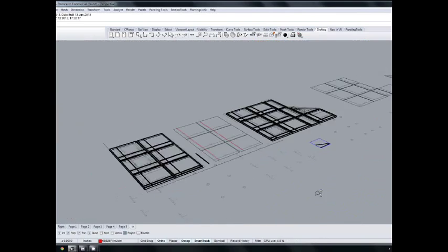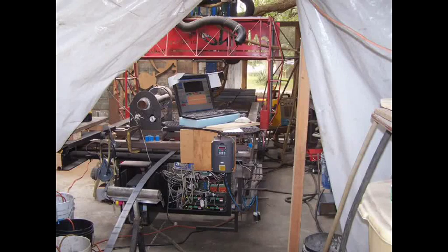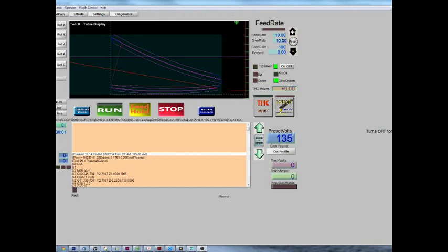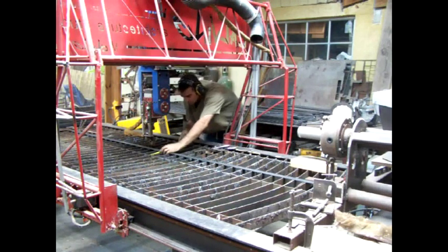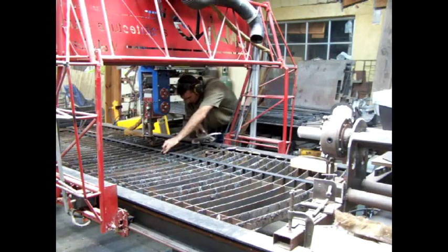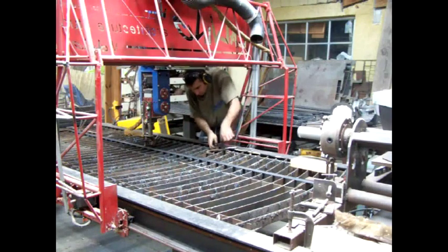So then this was fabricated, probably using CNC technology here. We're cutting all the pieces. Some of them are tapered. And we're also using a flat bar. It's the most cost-effective way to do it, and I can get any shape and any angle. I can get a Z section